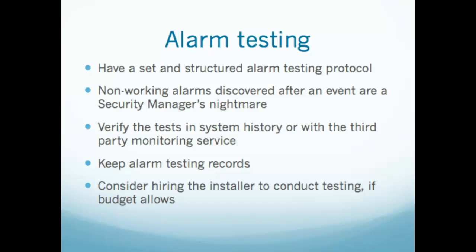You set up a protocol for how you want every one of your alarm sensors tested. How are we going to test the glass breaks? We're going to use a tuning fork and we're going to shake them. We're going to use a device that slaps against the glass that gives it the right vibration so it sets these bugs off. We're going to have a guard walk the fence line and walk in and out of the microwave beam between every sensor and make sure that it gets set off. You have a structured testing protocol and you do it on a regular schedule.